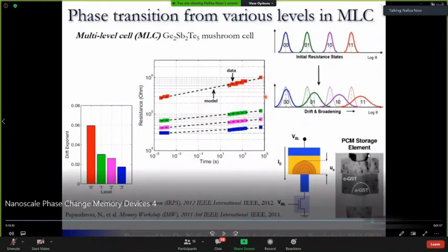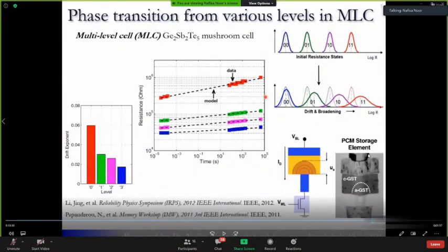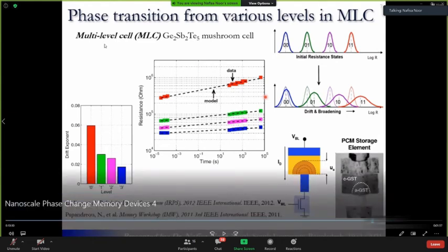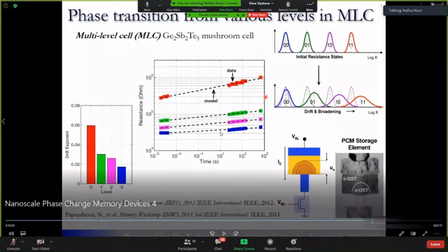This is a very interesting thing, and here you would see that the PCM has a serious limitation, or any type of resistive switching memory has this limitation in the MLC operation. MLC operation is the multi-level cell operation. When you operate them with these many levels that are too close by, what can happen is that if the resistance is drifting over time, then these bits will be mixed after a certain time. For example, between the blue and the pink, the threshold is here, and that's how you are going to distinguish these two states. But if you keep the same static threshold after a certain time, the resistance has already increased in the blue. So right now, the blue is no longer in its defined state. So you would see that the levels are mixed after a certain time if there is resistance drift in any kind of resistive switching memory. So that becomes a problem.